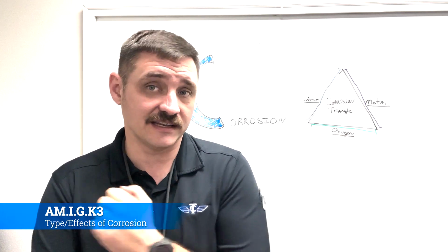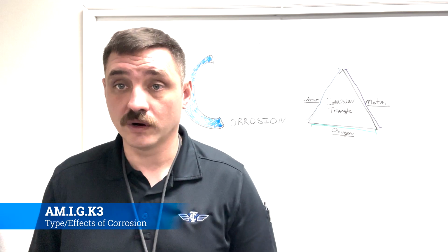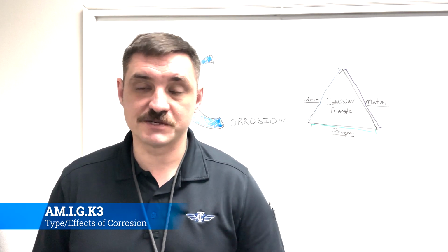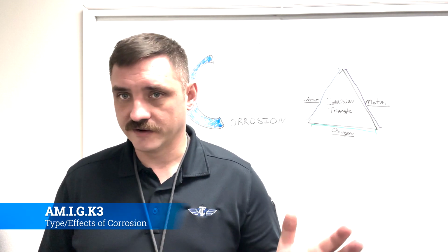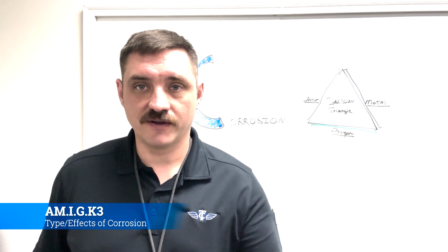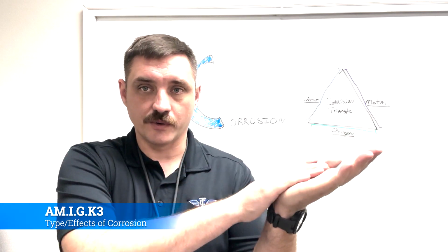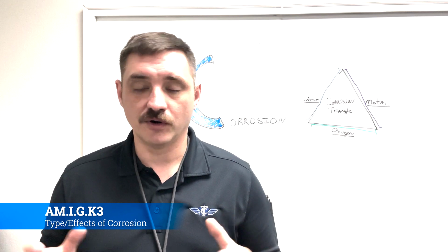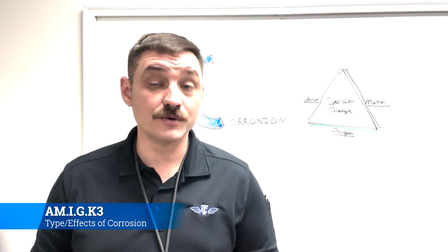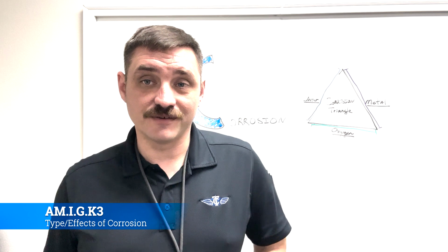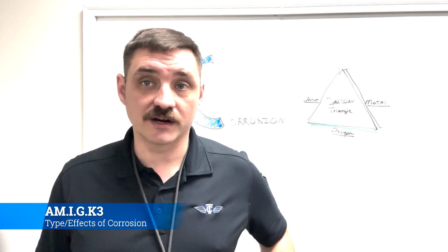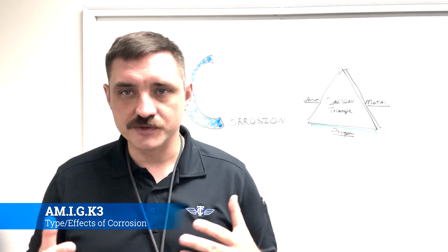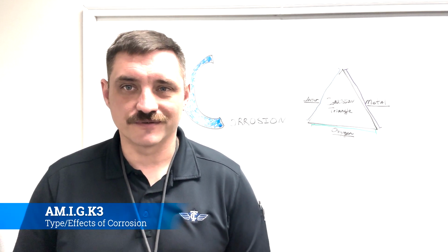It's like battery acid getting leaked onto metal, or some brazed joint with a bead that flew off, and now that spot's starting to corrode, or whatever. It basically means that you have a metal, and then you have some sort of chemical going on to said metal causing corrosion. Most of the time on modern airplanes, this is the type of corrosion that you will generally see, and it's usually from something that somebody spilled somewhere or got careless with, because it's engineered with corrosion in mind to try to keep corrosion from becoming a thing.